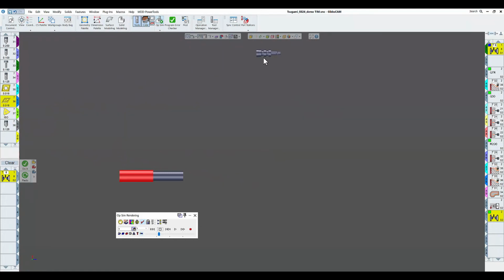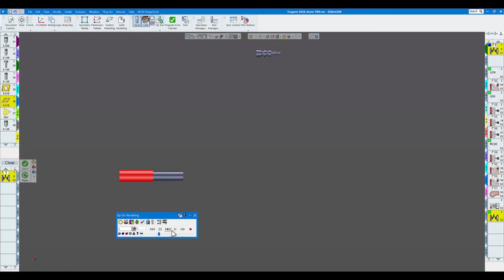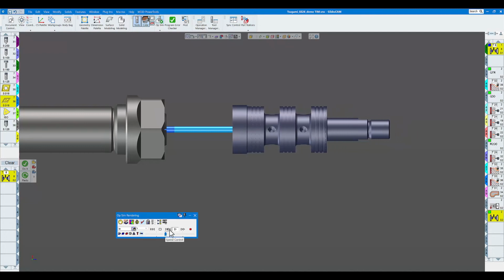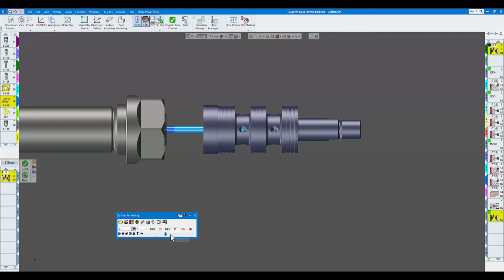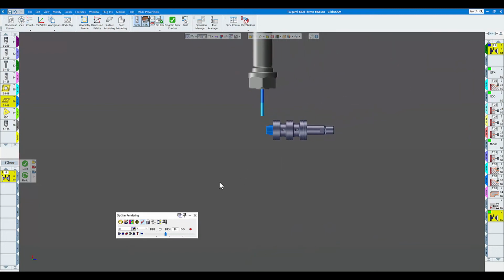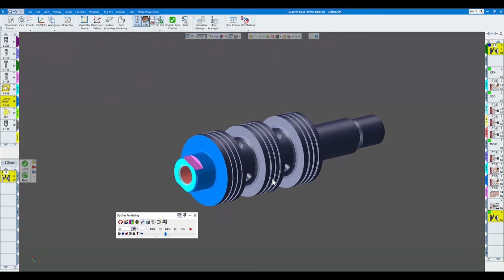Now this is where our part is in the sub spindle, but it is going to come over here because in one section of this we're going to drill with the main spindle and sub spindle, so you'll see it kind of jump over there after it faces off, and then it's going to go back over to the tools on the sub side, so we'll zoom that up there, speed it up a little bit. Of course, roughing, finish, cut our flats, and there's our part on the sub spindle there. So that's our finished part there.